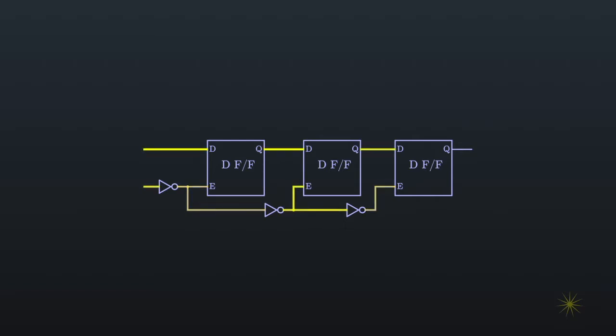The clock signal goes high, and the contents of the first flip-flop is then allowed to be copied into the second. However, because the first flip-flop is no longer enabled, changes to the data line do not alter the contents of the second flip-flop. The clock signal then transitions from high to low, and that allows the contents of the second flip-flop to finally be stored in the third, which is now output by our new register gate. The data line does not affect the state because at this point the second gate is no longer enabled, so it no longer changes state as the data line changes state.